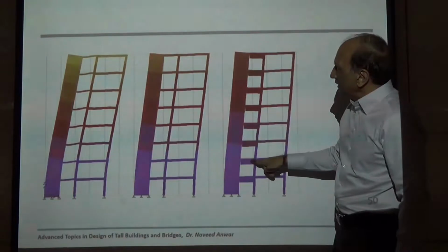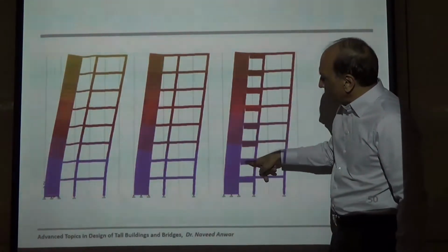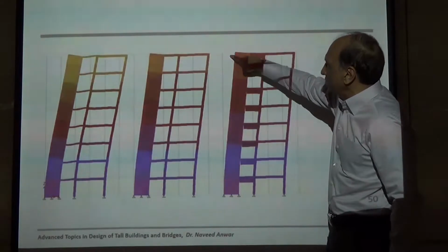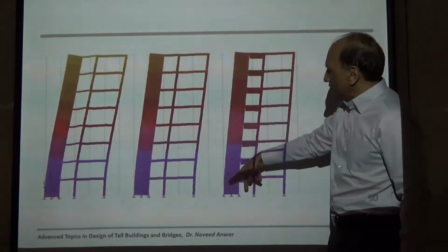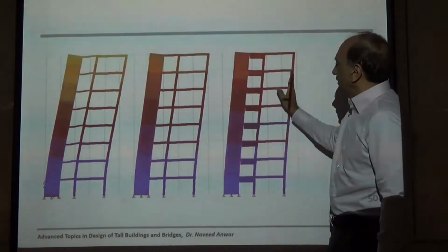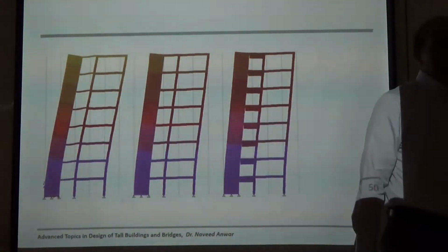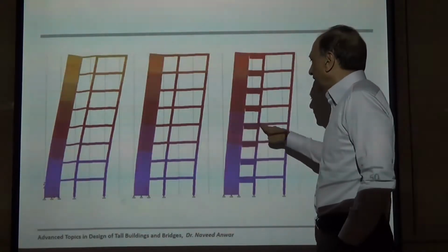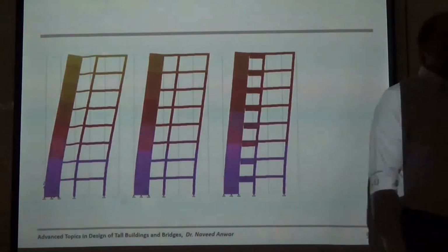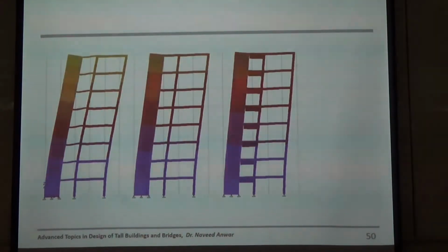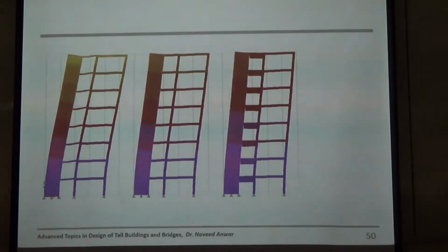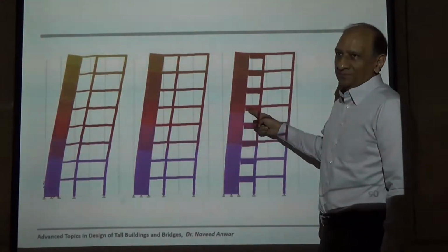And when I increase the size of this one, now you can see the deflection has reduced a lot, and at the same time the pattern of the frame deformation has changed a lot. Which means this connection between this wall and beam is very critical to utilize the frame-shear wall interaction. These are normally called link beams or coupling beams, or coupling between wall and frame or between wall and wall. And this is a very interesting problem.